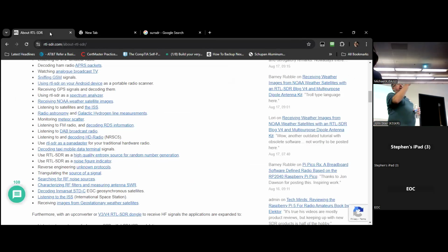So as you can hear in the back, that is the interconnect being received via an SDR. Running SDR trunk, you can get away with one SDR for both your control channel as well as your talk groups. The problem is that if you only use one SDR, you listen to the control channel and one of the talk groups will come up, Hurst, Bedford, Euless, whatever. They'll be having a conversation, and as soon as the control channel picks up another talk group's activity, it'll flip.